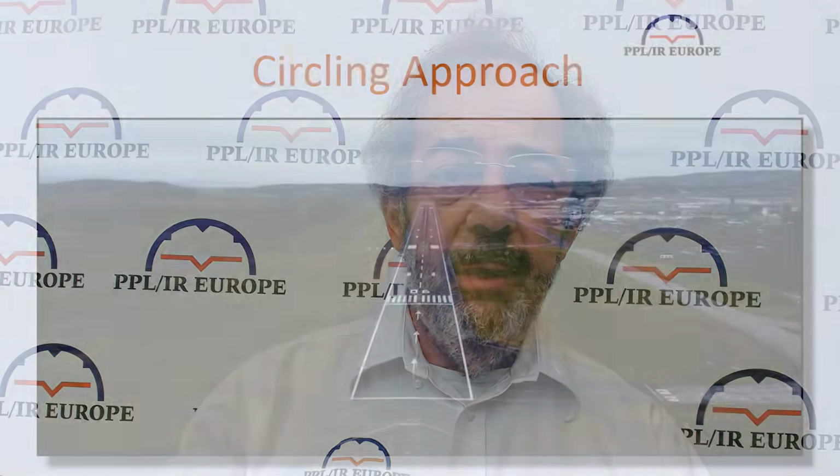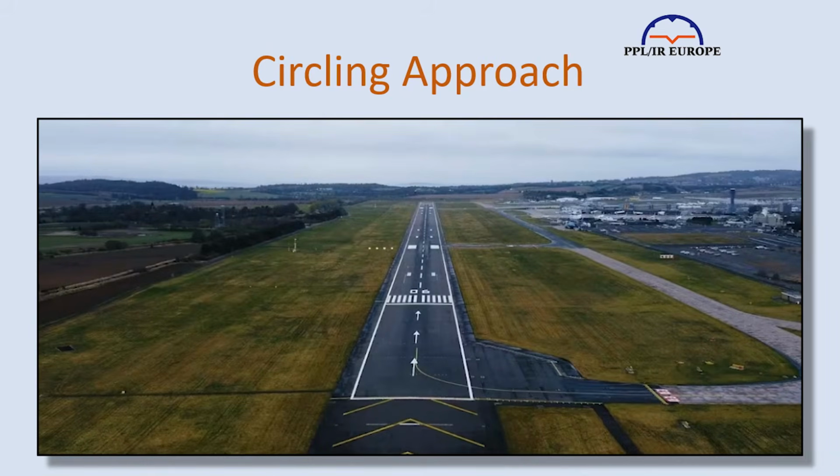On the other hand, if cloud base and visibility is not an issue, there's nothing to say that you need to descend to circling minima before starting the circle to land. Indeed, you may well simply descend to a circuit altitude and perform a normal VFR circuit if you're happy that there's no chance of re-entering IMC.